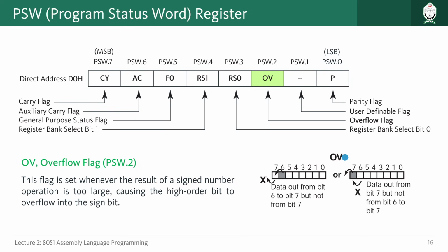But basically, in general all the unsigned arithmetic will happen for the total 8 bits, from 0 up to 7, all of the bits are used for arithmetic operation. But whenever you have an operation where we are using signed arithmetic, the last bit or the most significant bit will be used for the sign, plus or minus, right?